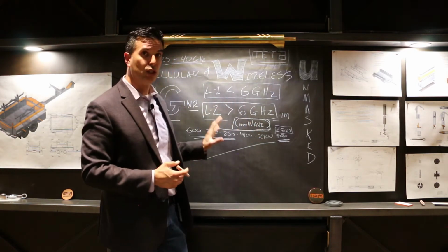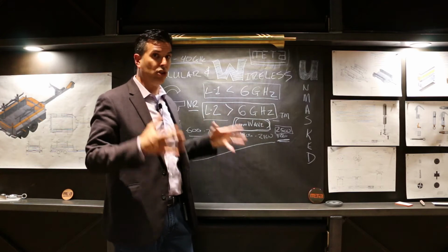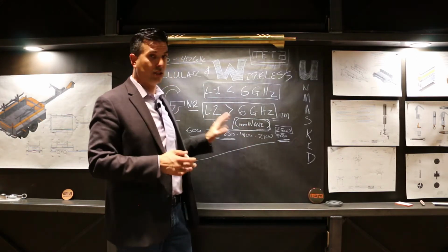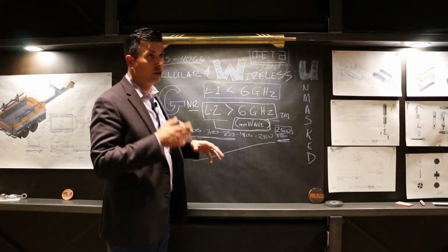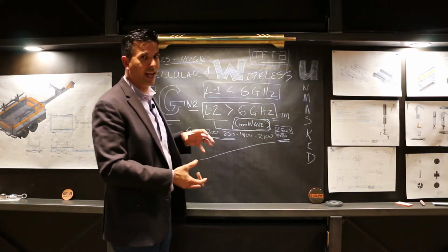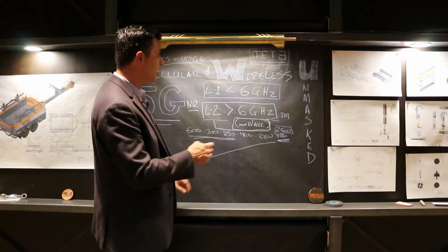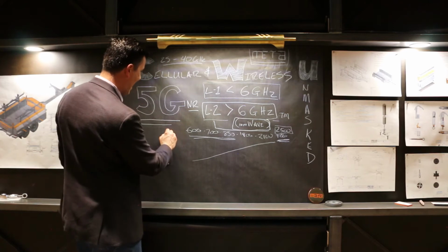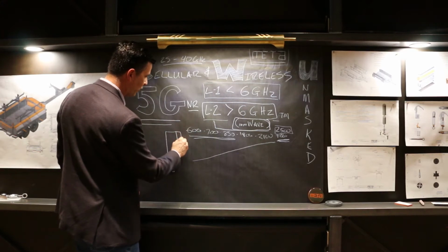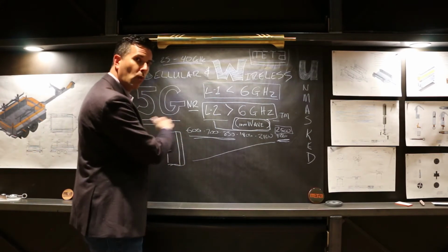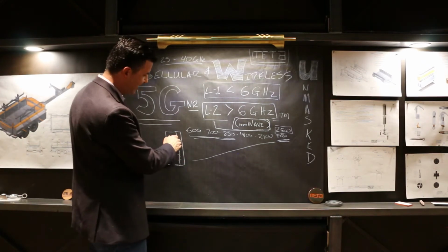This is relatively unused spectrum, so the cellular operators took those large chunks of spectrum in the millimeter wave band and said, let's use those for our 5G services. And these are the impressive 5G, the level 2 stuff. You'll notice it on poles because you cannot separate the antenna from the radio with coaxial cables like you do with 4G. The radios typically used for millimeter wave are active antennas. So you have your radio and your antenna is basically the forward section of that radio. So it's all one unit. You've got very, very tiny sections of coax that connect the antenna to the radio.